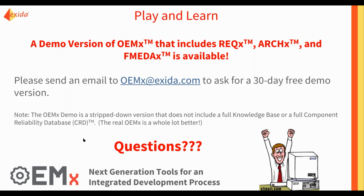So we've taken the approach that we will use the 61508 concepts for the analysis because those failure modes are orthogonal and complete, whereas 26262's are not. And then the FMEDAX tool automatically translates from 61508 into the ISO 26262 metrics. So the bottom line is it's not one or the other, you get both. But we're using the superior analysis definitions from 61508. Good question, thank you.